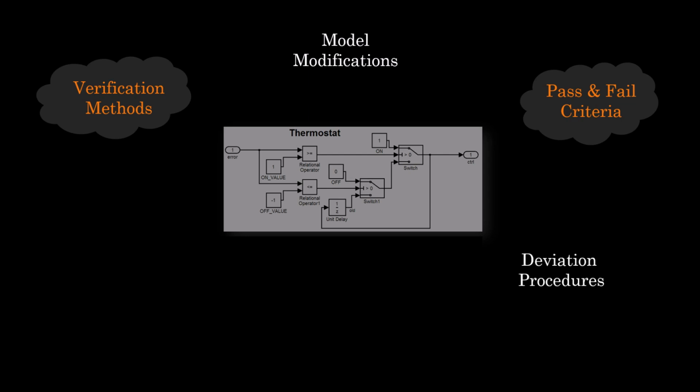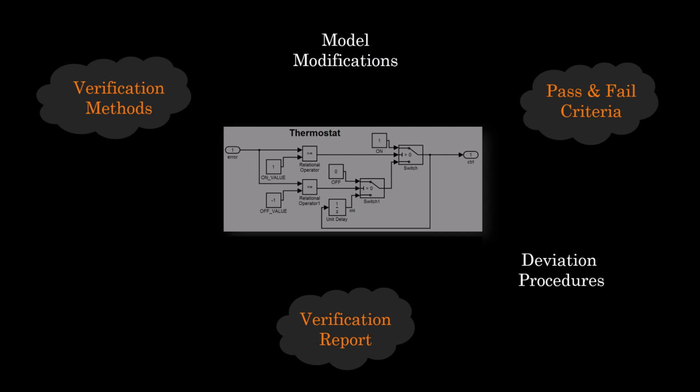Some deviations from the expected results are acceptable or even necessary for safety-related functions. Such deviations need to be documented. The resulting verification reports shall include sufficient evidence of positive results and full coverage of requirements, structure, and other verification methods. All the verification steps will be repeated after every model modification, so tool automation is a must for dynamic model analysis. The criteria to choose the right tool for dynamic model verification are defined in ISO 26262.